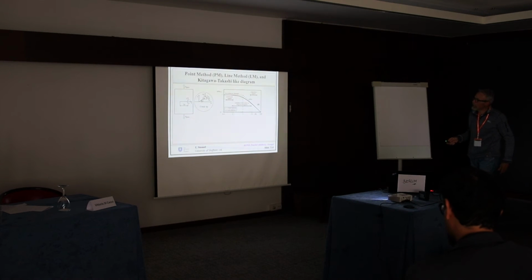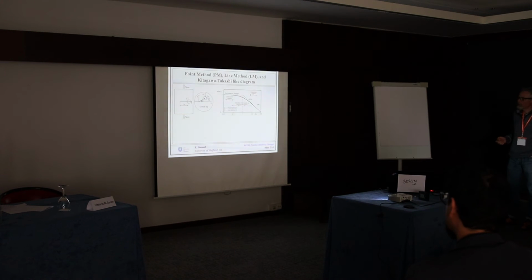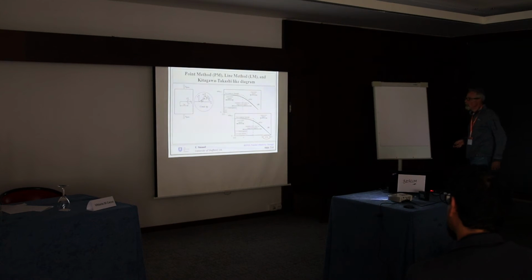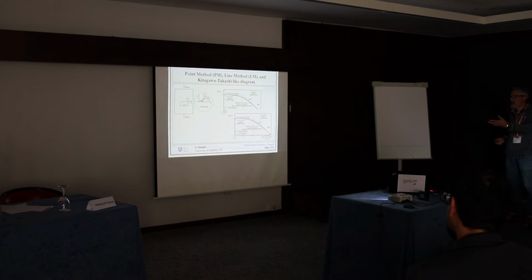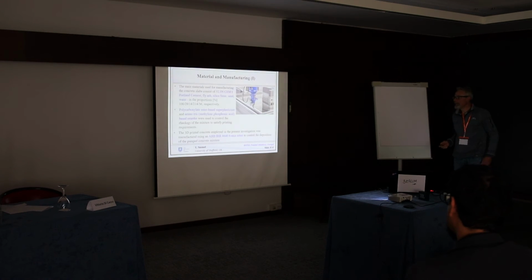Basically, they link the plain material behavior with the behavior described by linear elastic fracture mechanics. Here is the case of an infinite plate containing a central crack loaded in tension, but if we play the trick of using the equivalent crack length, that is, we bring into play the shape factor, we can extend this schematization to any possible configuration, and the shape of the curves is always the same. So now all the ingredients we need are there.